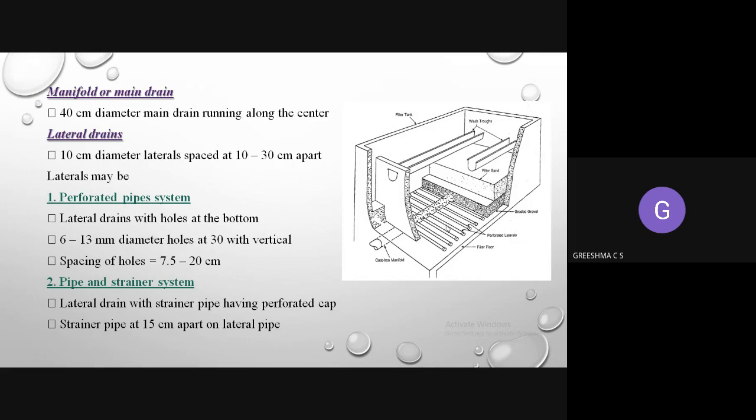Holes of 6 to 13 mm diameter will be given at the bottom portion of these lateral drains. The spacing of these holes will be 7.5 to 20 centimeter.